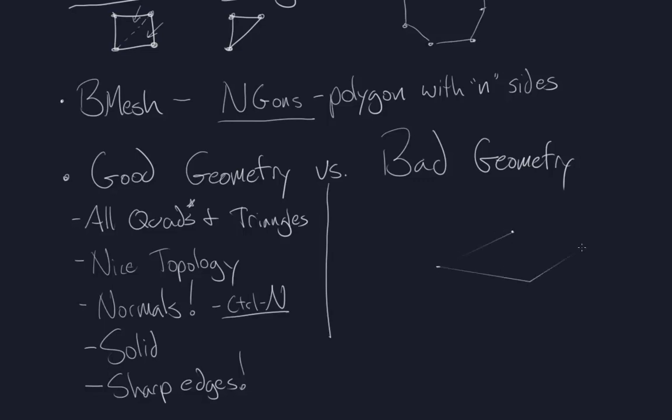So, let's say I've got a cube that I just modeled out inside Blender, or I just created, you know? By default, all of the edges inside of Blender are 100% perfectly razor sharp, and that never happens in the real world. In the real world, even if you have a reasonably sharply modeled cube, very likely, if you were to get close enough to it, you would notice that the surface exhibited a little bit of rounding at some point, allowing you to get a little bit of a specular highlight right there on the edge. You never have perfectly sharp edges in the real world, for any reason.